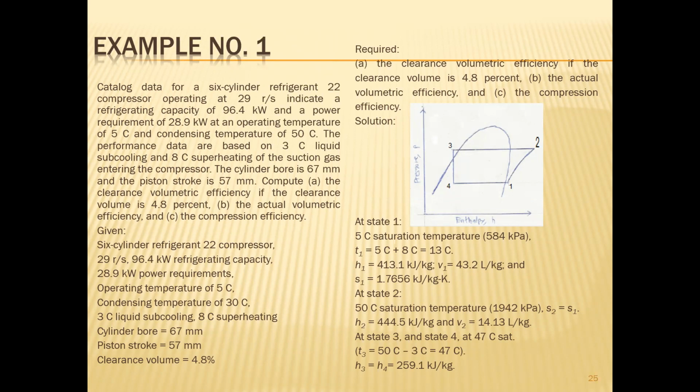96.4 kilowatt refrigerating capacity. 28.9 kilowatt power requirements. The operating temperature of the evaporator is 5°C. Condensing temperature is 30°C. 3°C liquid subcooling and 8°C superheating.